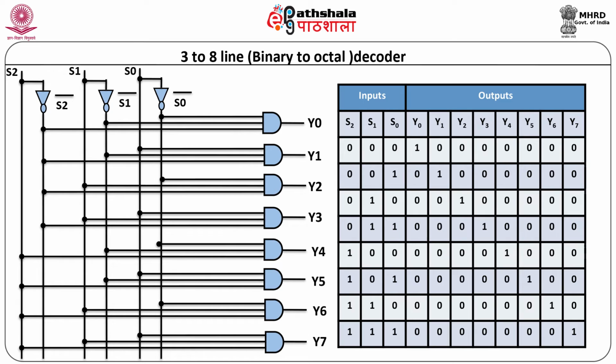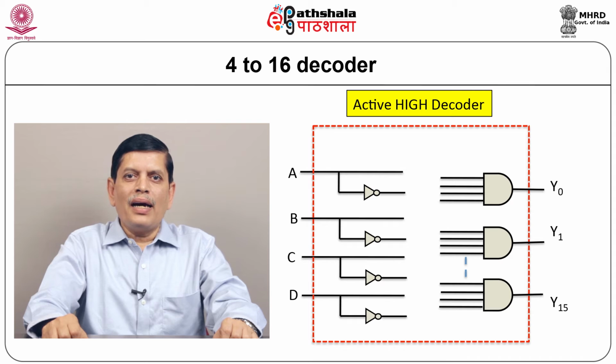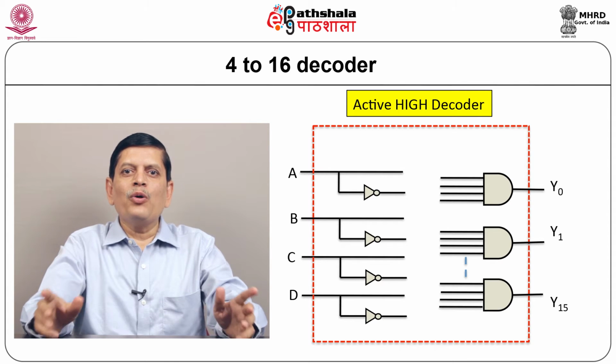or not. In many decoders, there is an enable function, a low level on inputs E1 and E2 and a high level on the third input, that is E3, is required in order to make the enable get active high to enable this decoding action. These three enable inputs are extra other than the binary inputs. Let us now discuss the architecture of 4 to 16 line decoder.